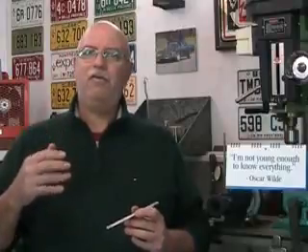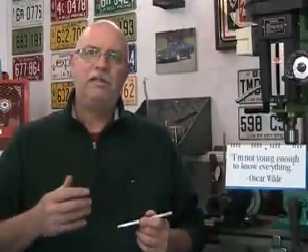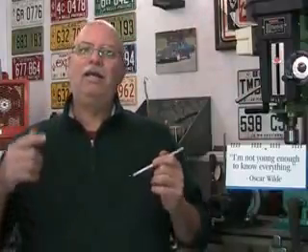But it's not just to save us from having to write bizarre or not very poetic notes on our drawing. It saves us money and time as well, because geometric tolerances permit us to make a part accurately without killing it with dimensional tolerances. What do I mean by that? Well, the block that we were just looking at, the 1, 2, 3 block, the V block.